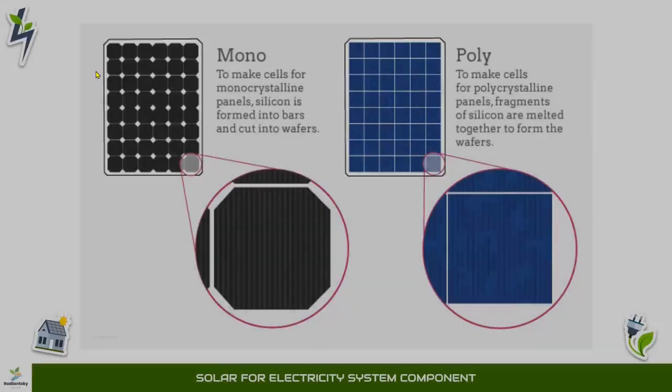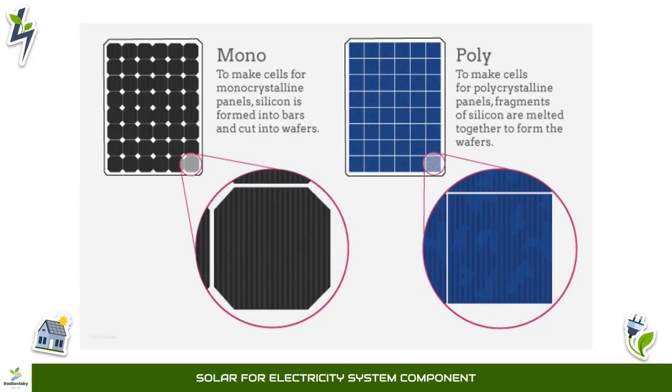Now, how do you differentiate poly panel and mono panel, which is very, very important? In the field today, you are going to be experiencing these two panels. In fact, in a country like Nigeria where we are, poly panel is now being outdated. What you find most out there is mono panel with the different models I showed you, with that PERC model, with half cut, with bifacials, different types of models of mono panel. That is what you find there.